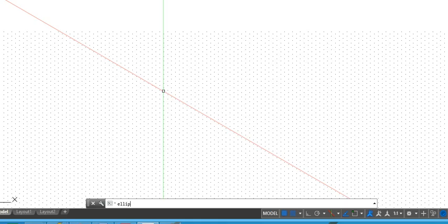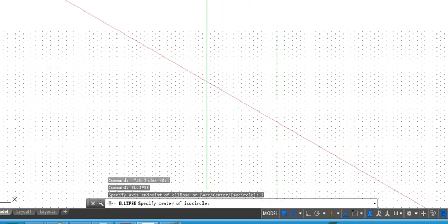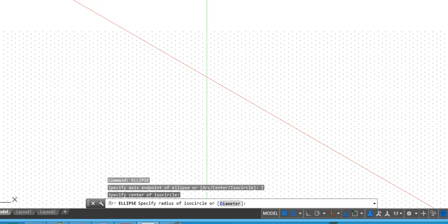In that case, we proceed with the ellipse command, because in isometric drawings the circles will look like ellipses, but ellipses of a very special type, which is called an isocircle. So we will choose the isocircle under the ellipse command, and we are into the isocircle command, and we decided that the radius of the disk which will be visible from top view is 3 grid spaces.